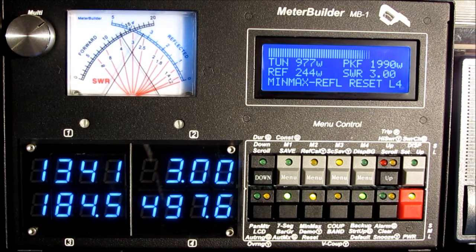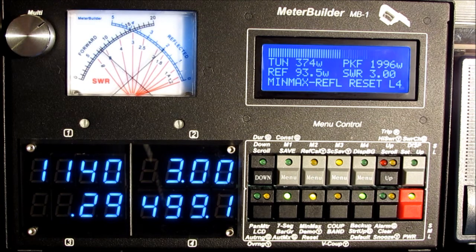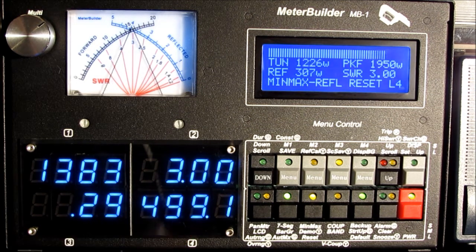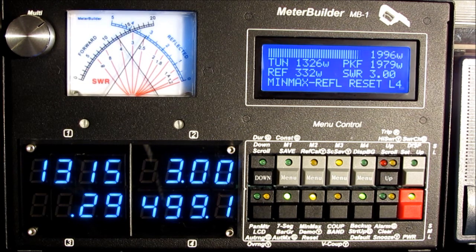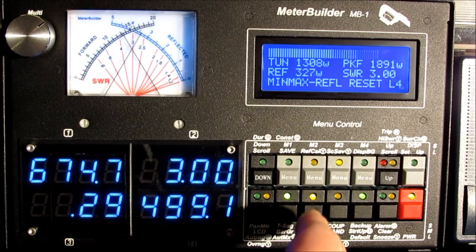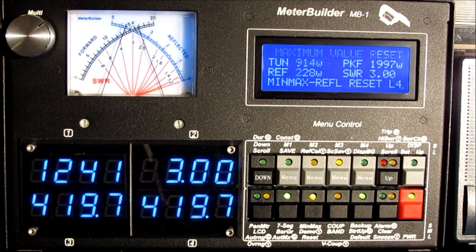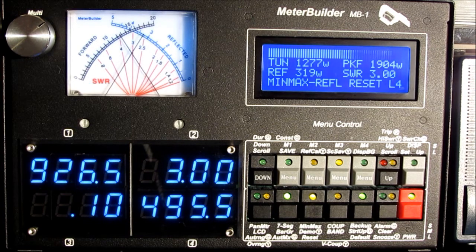This is the min and max of the real-time reflected power, and this is a little interesting. We have 2000 watts full scale forward power. We have an SWR of 3, and you can see that our reflected value is approaching 500 watts, and 500 watts is the correct value you would have when you have an SWR of 3 and a forward power of 2000 watts. Again, let me go ahead and reset it. See if those numbers converge back to that category. And again, you see that they do. Okay.